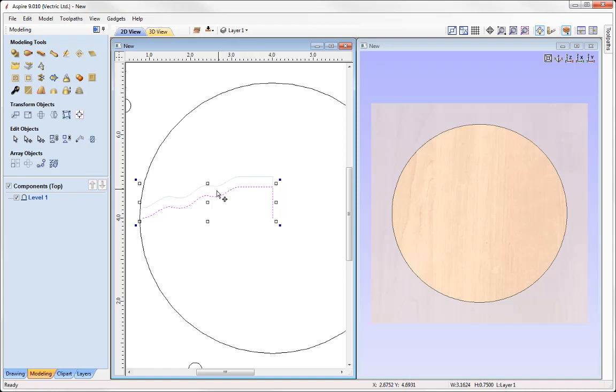And so here, like you saw in the introduction, what we're actually seeing here will be the actual thickness of our bowl as if we was to cut it in half. Okay, and so that is our thickness, and it should be 1/4 of an inch because that's how much we chopped our vector up by. So we got rid of the span over here and we brought the leg up by 1/4 of an inch.